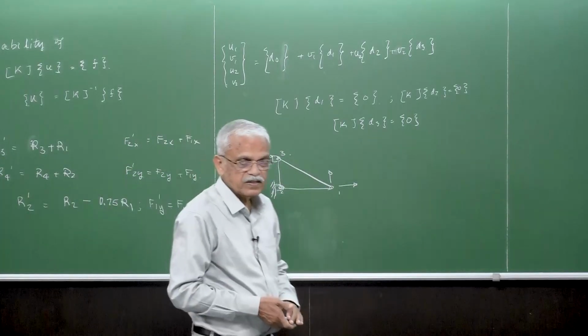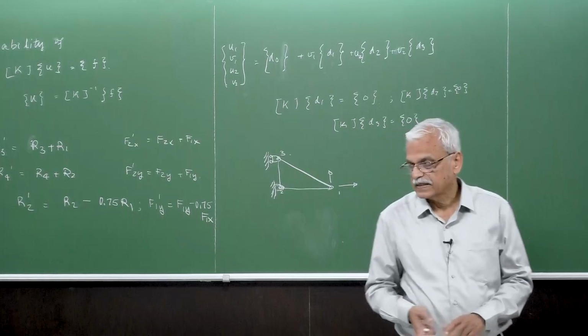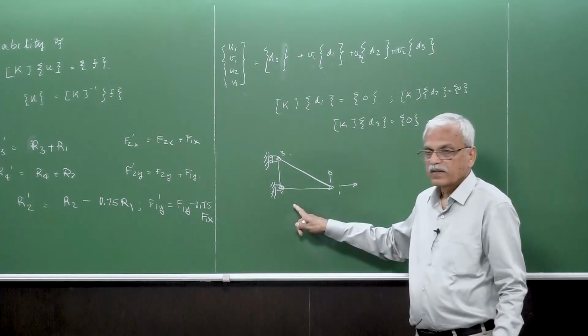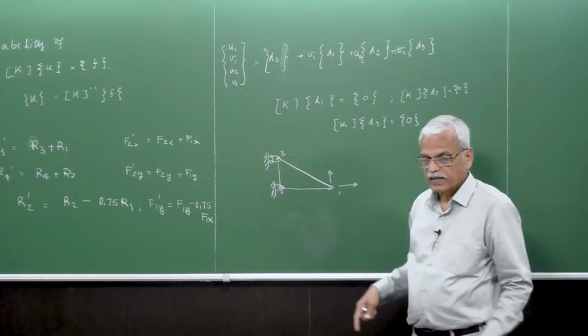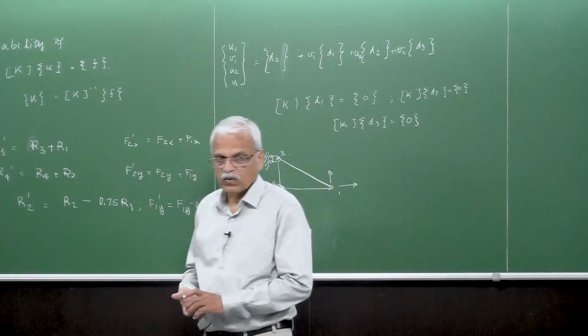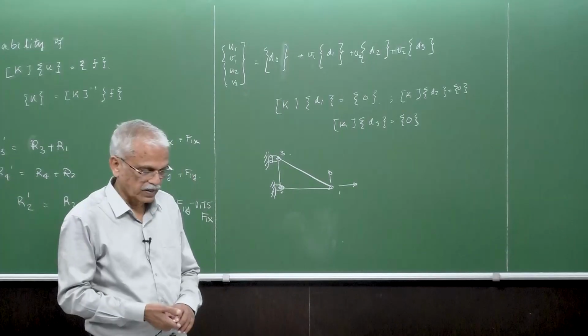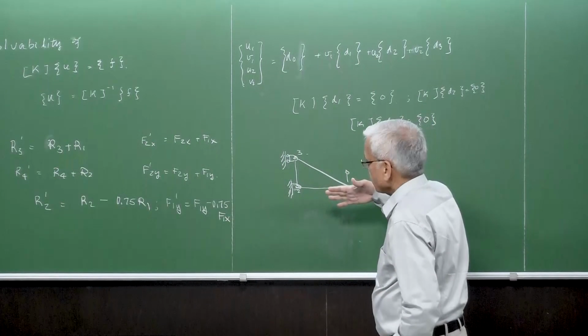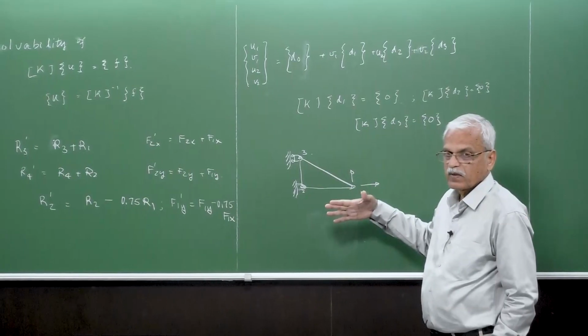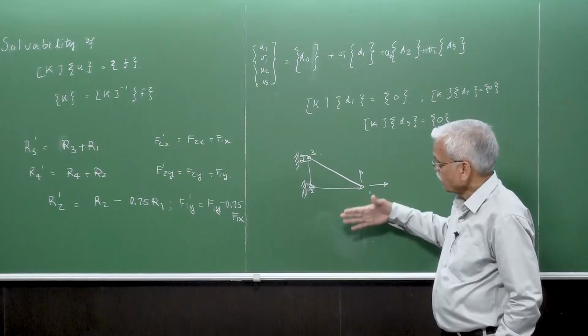So that means the rotation is also constrained. That way we have to judiciously apply the boundary conditions so that all the rigid body modes are removed.